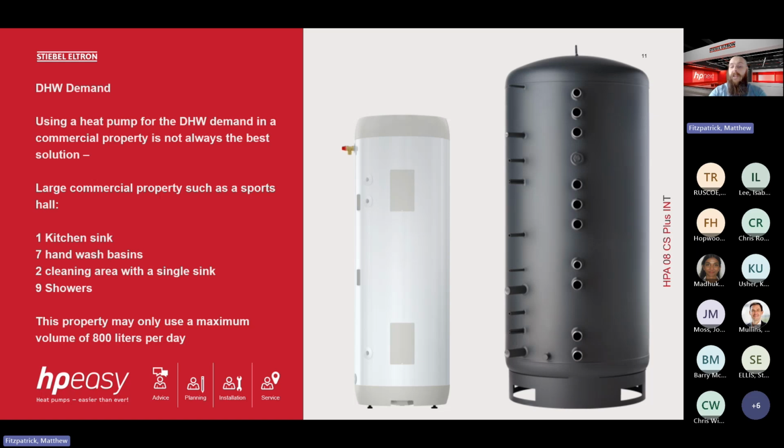And we can maintain a high level of efficiency with an air source or ground source heat pump. In some cases with commercial ground source heat pumps, especially considering ours, we have a feature called hot gas, and it allows us to feed the domestic hot water cylinder with energy, with heat, and reheat that cylinder whilst we are still heating the property. So we're operating in 2 modes at the same time.